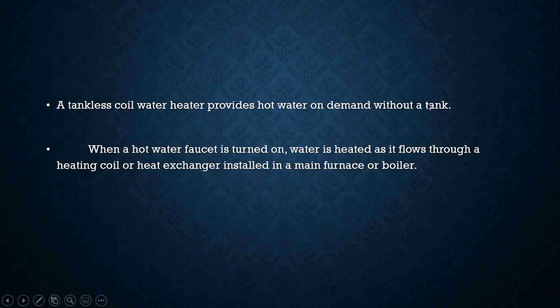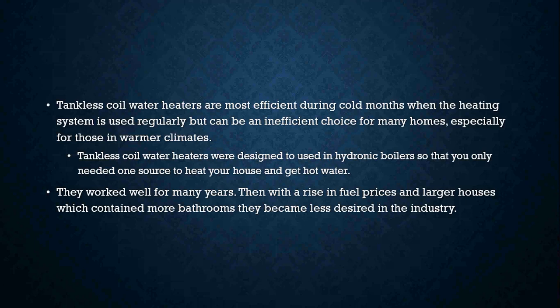Okay, tankless water coils provide hot water on demand without a tank, and when a hot water faucet is turned on, water is heated as it flows through the heating coil or heat exchanger installed in the main furnace or boiler. Tankless water coil heaters are most efficient during cold months when the heating system is used regularly, but can be an inefficient choice for many homes, especially for those in warmer climates.